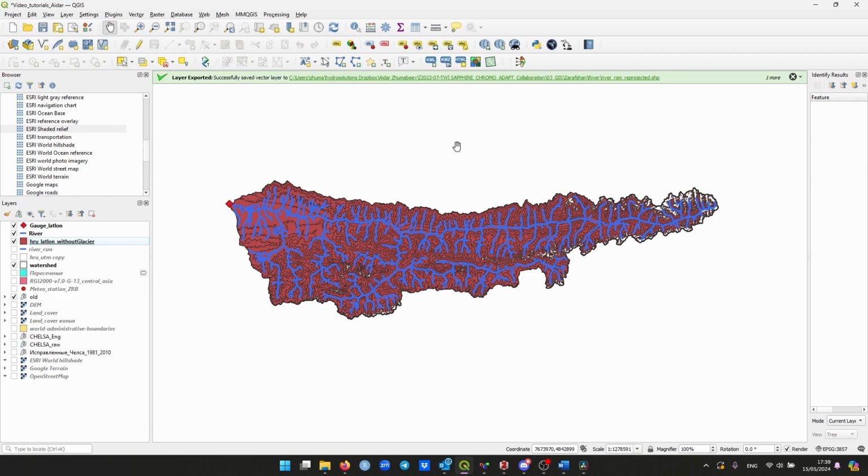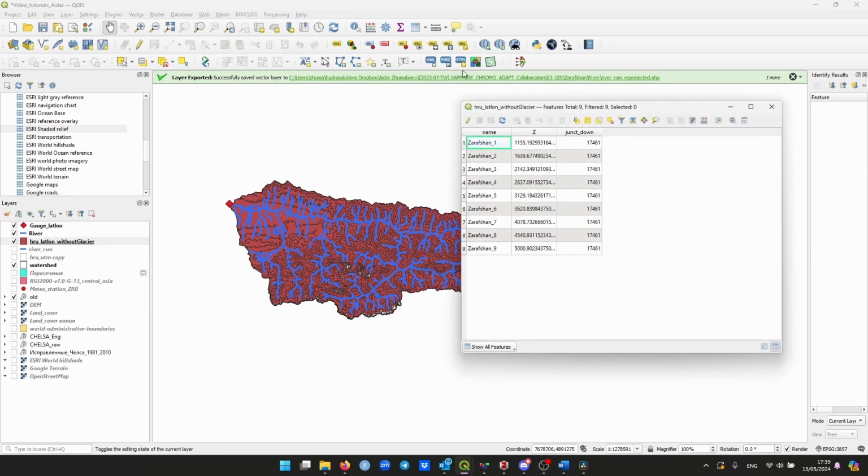First of all, we need to prepare our shapefiles because the RS Minerve model creation tool uses the GIS files to create a model. Let's look at our HRU shapefile in QGIS and open the attribute table. It needs to have important information in three columns.